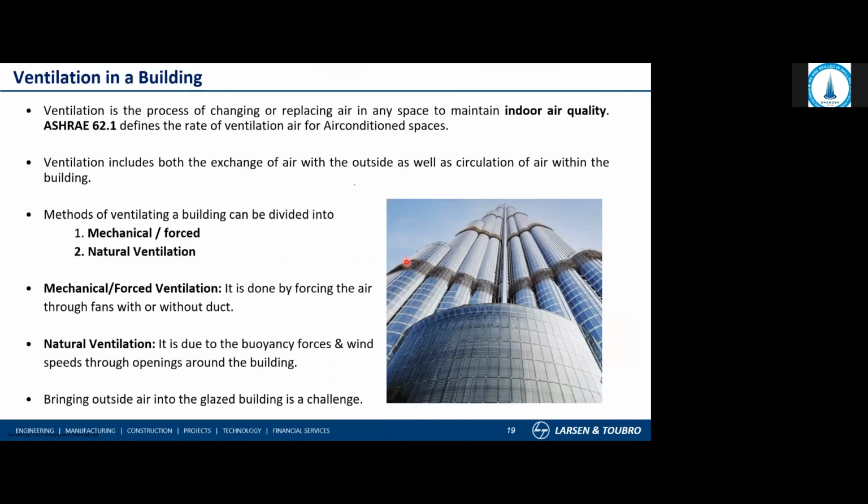Now, ventilation is very, very important for any building. Ventilation in terms of ratio for air conditioned space is something we follow as per ASHRAE 62.1, which gives the guideline depending upon the application. If you see this kind of building with a complete glazing facade, there is no space to accommodate any element apart from this. Within this challenging facade, we have to incorporate the fascia, which we have to take from outside. Basically, external louvers will be provided. External louvers are one part we have to discuss with the architect and provide in suitable locations as per the aesthetic requirement of the building.